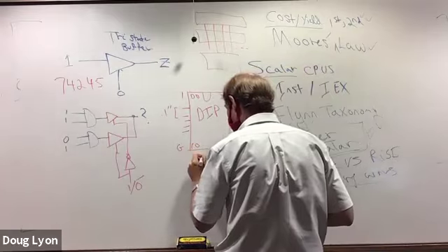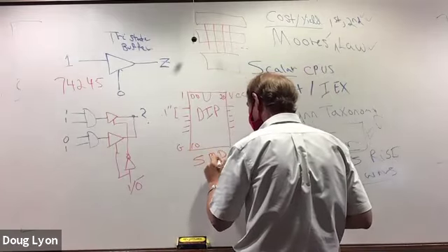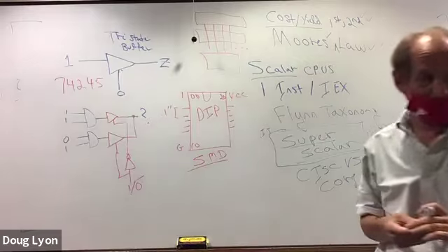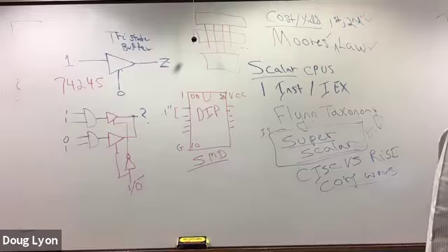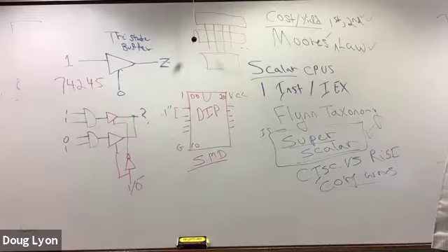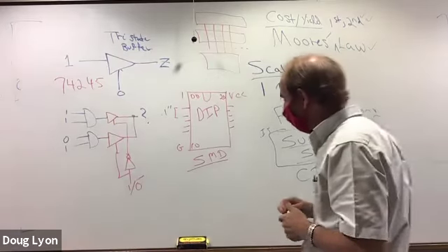surface mount devices, SMD. Because surface mount devices are meant to not have pins that go through boards, it allows you to avoid having to drill holes. If you've ever made a printed circuit board and you sat there with a drill press, as I have done, and tiny little drill bits that break all the time, and you start drilling holes through the fiberglass and epoxy printed circuit board substrates, it's not pleasant. And turns out it's terribly time consuming.